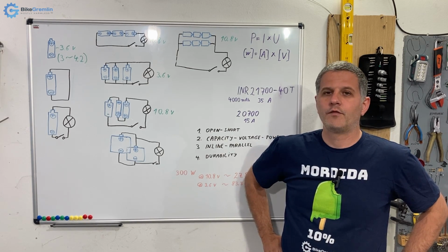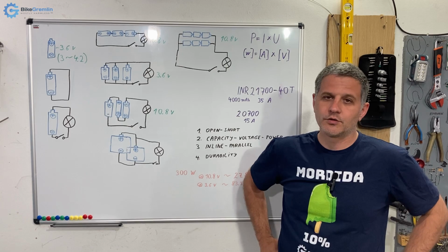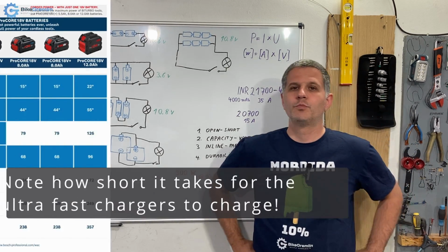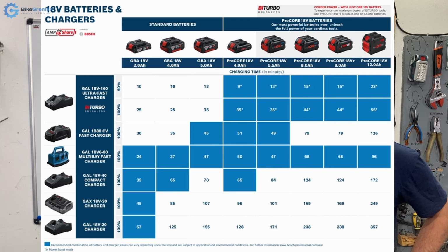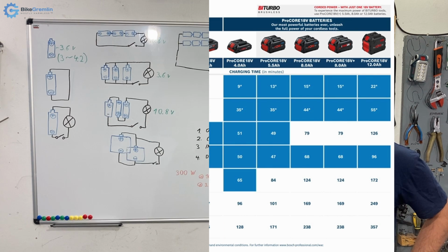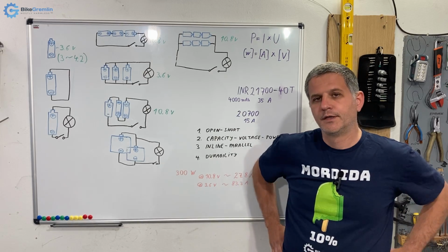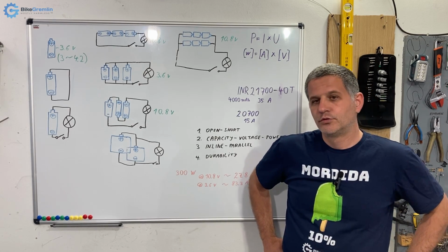So a couple of hours on a charger is okay, it's not too fast, but still those super fast chargers that will charge a battery from empty to full in an hour or less, they will also increase the degradation of your battery. So it is a trade-off. And those are things to look out for.